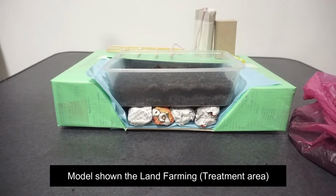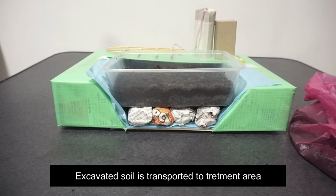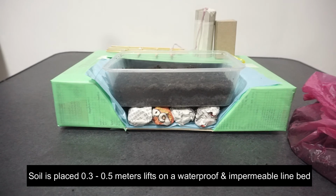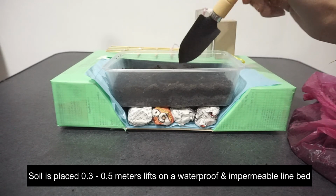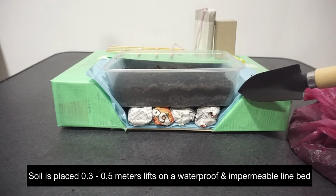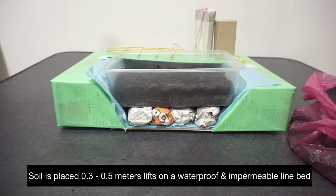Now this model shows the treatment area, which is the biofarming treatment area. The pre-treated soil is transported to this treatment area, and the soil is placed about 0.3 to 0.5 meters deep on a waterproof and impermeable liner bed.